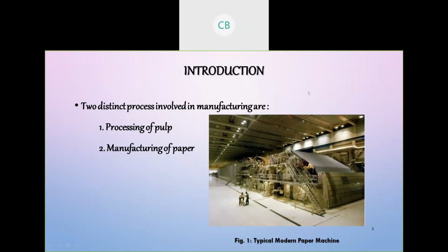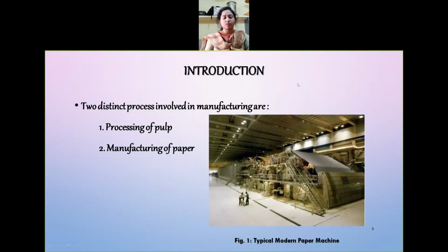Chemically, a solution is used to divide the fibers from lignin, and they use two types of machines. One is the fourdrinier machine and the cylinder machine. These are the two machines which are used in the industry. Usually, pulp stock is prepared for the formation of paper, either by beating or by refining. Refining is done through chemical processes which need to be continuous.